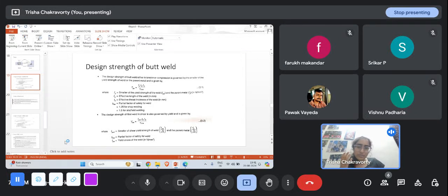But there were formulas to connect that to stress. Remember the My by I formula to get the bending stress. Similarly we had VQ by Ib to get the shear stress. So whatever the source, ultimately it is the stress developed in the material, and if that exceeds the yield stress, the material fails. Yield is not related to tension or shear. Yield can be due to anything. Okay, tensile yield, shear yield.